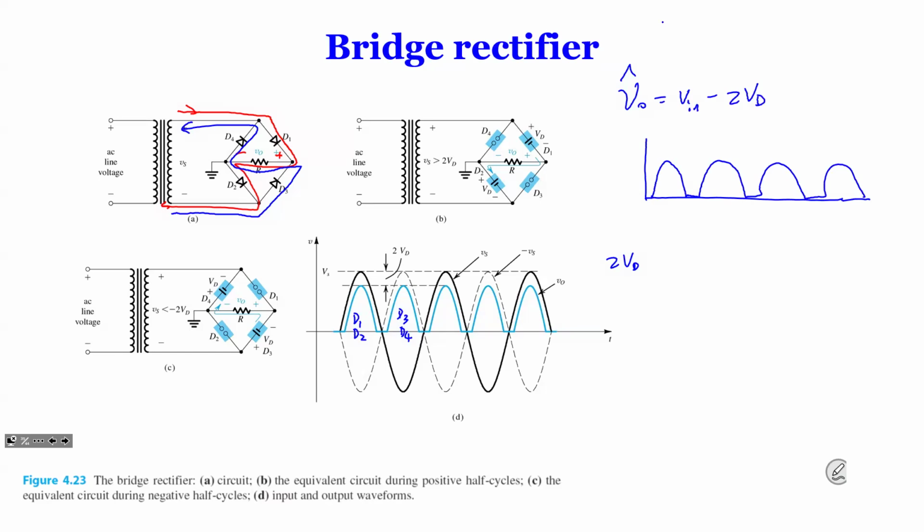So this is a very useful rectifier. Yes, go ahead. It seems like the full wave rectifier would be better. You don't lose as much power, but is this better because it's less strain on the diodes? Yeah, it's better because you get a full wave and you don't waste any of the winding voltage. Because in the previous slide, you saw only half of them is working at any given time. So ideally, the size of this one will be half the size of the previous one.